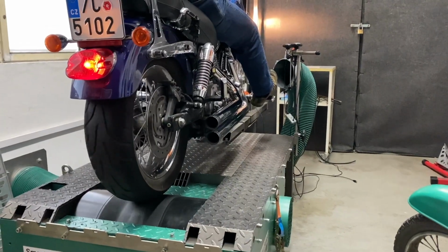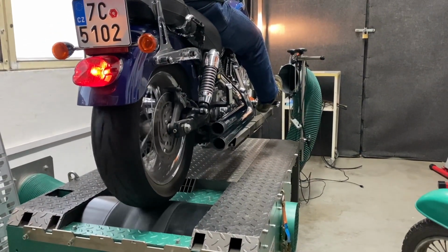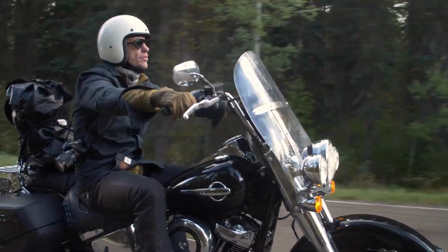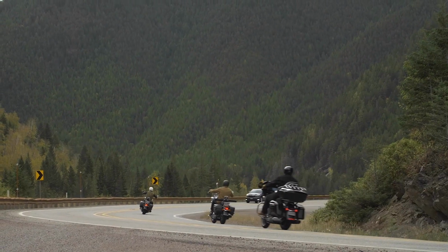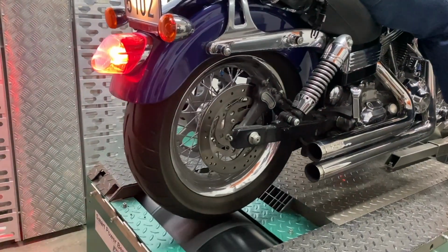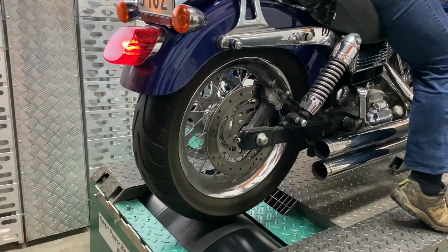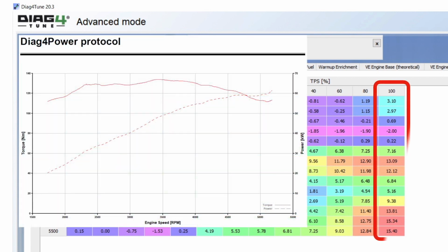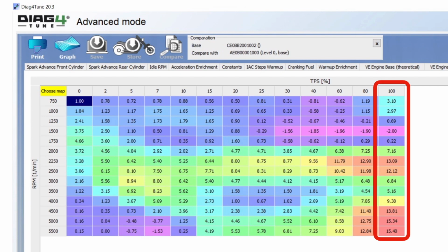Accurately measured VE values are thus the most important indicators for any tuning operator. Their greatest benefit is the fact that they describe the performance behavior of the engine across the full spectrum of the engine's operating modes simultaneously. Often, other presented engine performance characteristics describe engine behavior exclusively with the throttle valve fully open.